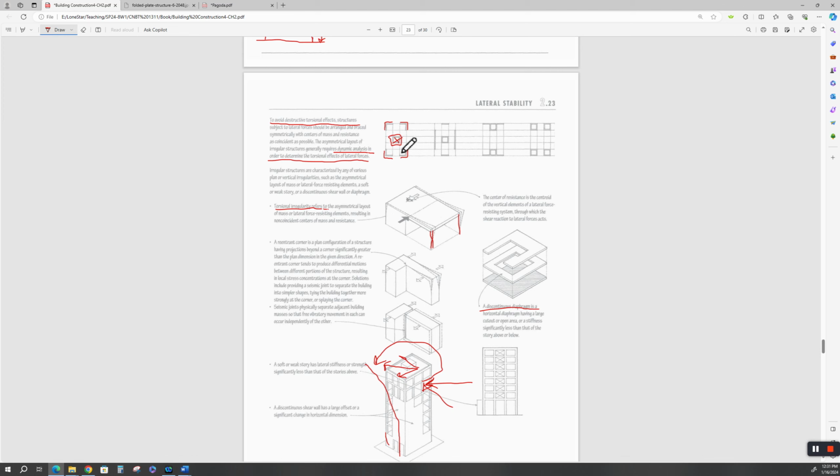So this would be like what? The pole going up through the pagoda. Okay. And these end walls are shear end walls, and they all will resist torsional effects. They'll resist just longitudinal, horizontal, and they will resist this thing trying to rotate around and twist apart.